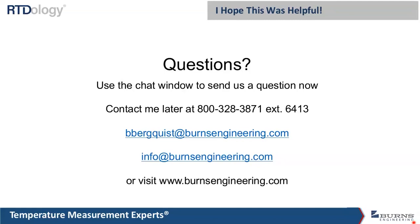And I'm also kind of reading ahead here. We have a question about connection heads and cleaning chemicals. Some of those chemicals, if you were to just use those on a regular exposed probe where the cable or lead wires are coming right out of it, can actually wreck the probe over time, because that liquid stuff is going to get inside and cause some shunting between the leads, resulting in a lower than actual temperature measurement.